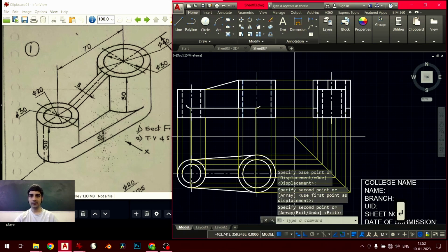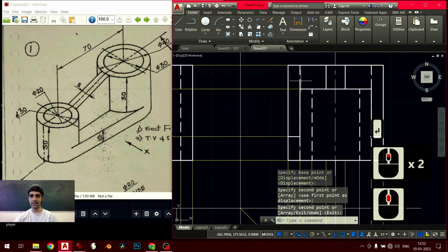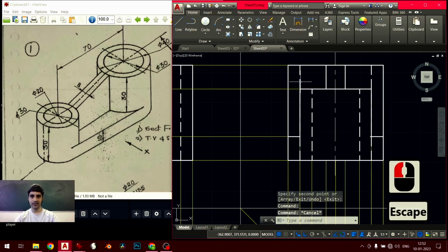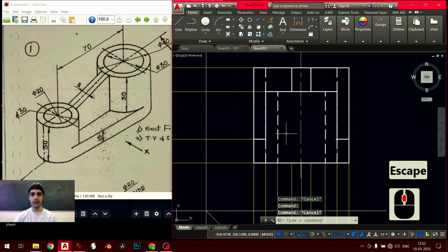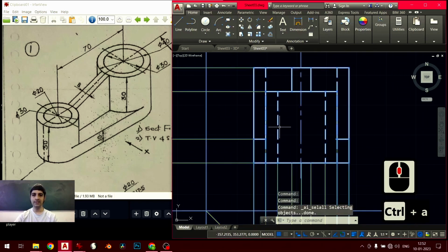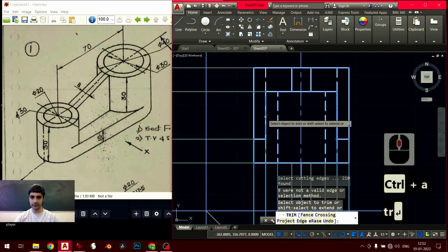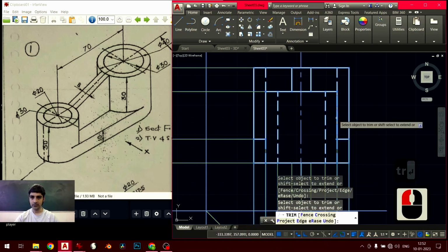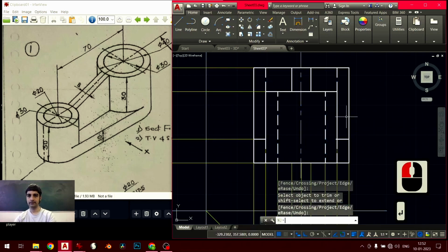You'll notice that there's a little bit of overlap between this edge, that's the hidden edge, and then this edge, which is visible. That happens often. In such cases, you're supposed to give preference to the visible edge. So I'll just trim off the hidden edge from here as well as here.